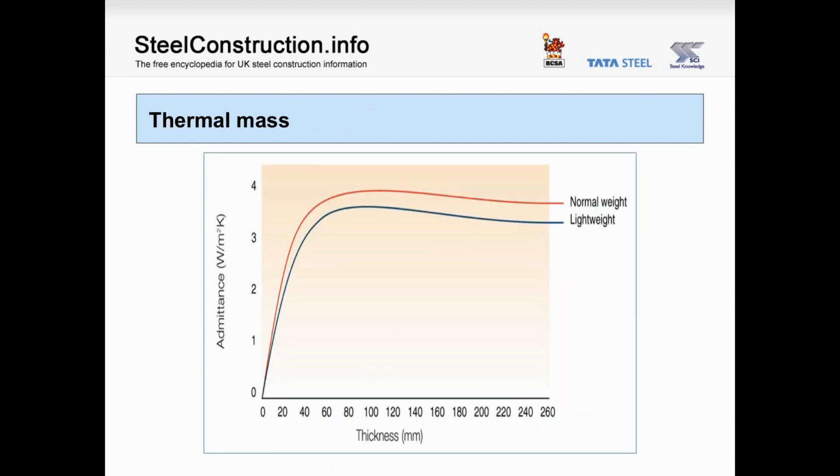Buildings are commonly designed with passive cooling strategies nowadays too. This is to take advantage of the thermal mass of the structure. This is a valid approach, but there is a misconception that we come across on occasion that using thermal mass would lead toward one type of frame material rather than another. In a building, the mass utilised is that of the floor slab.